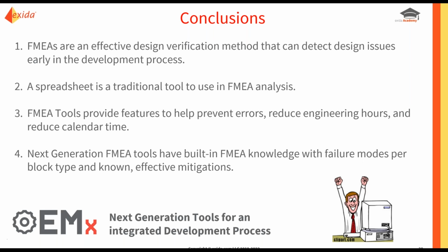I conclude then and emphasize that FMEAs are valuable. Sometimes they're a little painful and sometimes they're a little boring, but FMEAs can be and are a very valuable technique to identify design issues, and often it is well worth it if you find one problem. If you don't find any problems, that's wonderful, and now you know that you can move ahead much faster. If you identify problems, you can update your design right now before you even start detailed implementation.